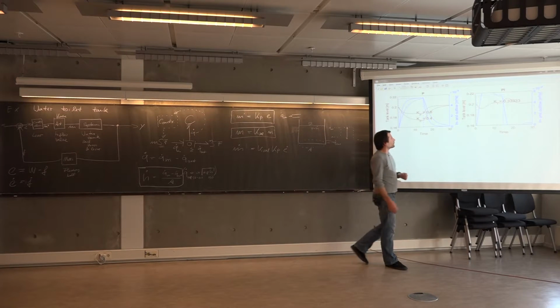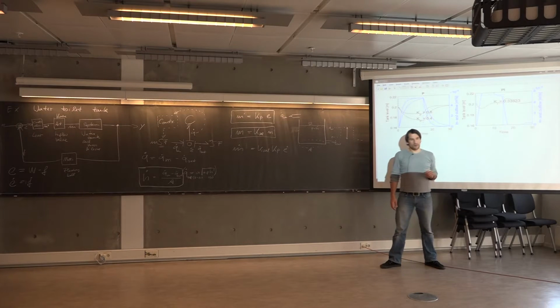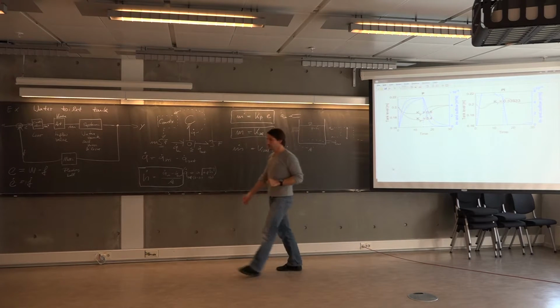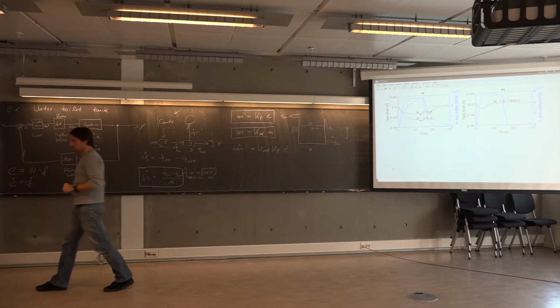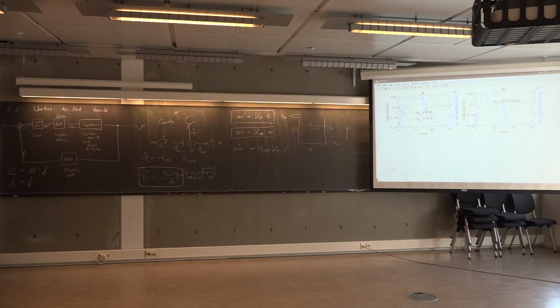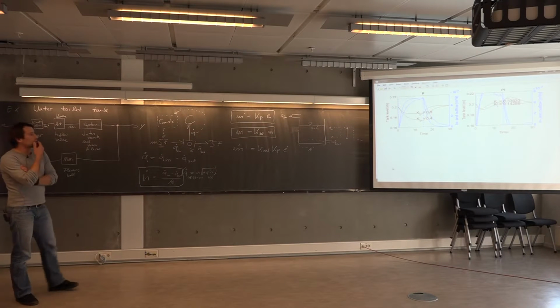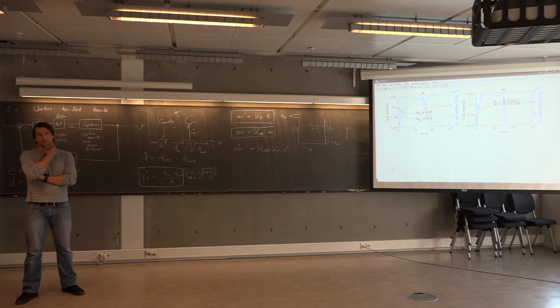The main point here, though, is that by adding this integral behavior, in addition to the proportional, one may actually get rid of this steady state error. Again, as with just the proportional, we can play around with the numerical values of this integral term constant ki, and by doing so, tune the behavior of the controller.